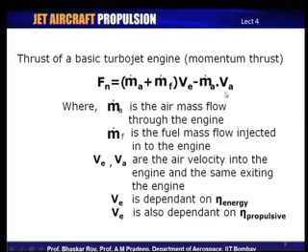And then the second term, you have the drag, what we would normally call a ram drag at the intake itself, which is composed of the mass flow that is coming inside the engine multiplied by of course, the velocity with which it is coming in.